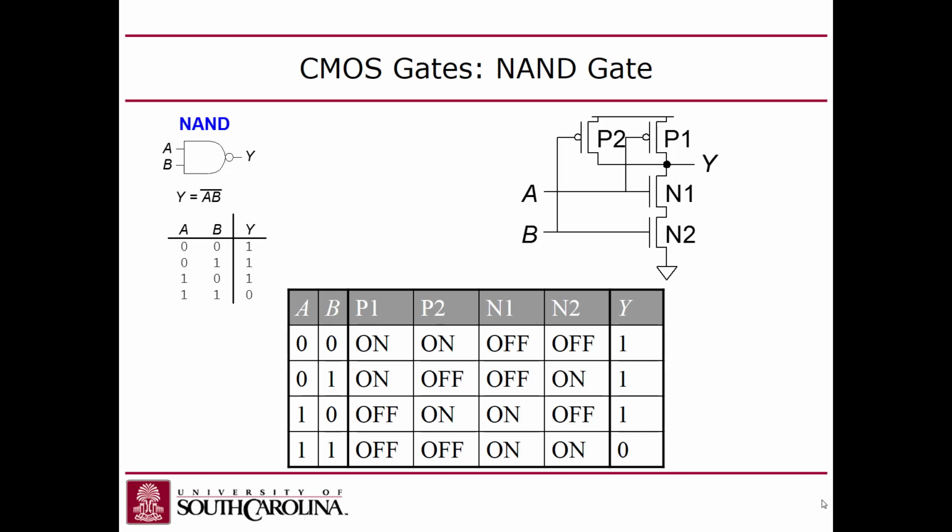So my output then is going to be 1, 0, 1, 0, 1, 0. So my output is going to be 1 under this case. So C would have to be 0, right? The bottom two should be 0, because A and B, right. That's right. Because when A and B are both 1, then we'll put a 1 into one of this NOR gate. Whenever you have a 1 in a NOR gate, then your output's going to be 0, right. You guys with me? Make sense?